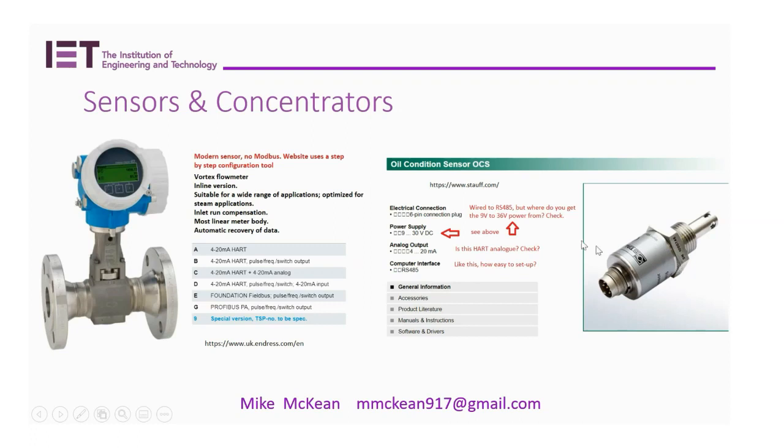And let me tell you why that's important. Rather than just changing oil because you've been running the machine for so many hours or so many days or so many revolutions, you're saying if you change oil too quickly, too often, and too regularly, you lose money. If you don't change it often enough, then the engine breaks and you've got a bigger problem. So what they do is install an oil condition sensor that says the oil is in this state, please change the oil in the next 2 months or something.